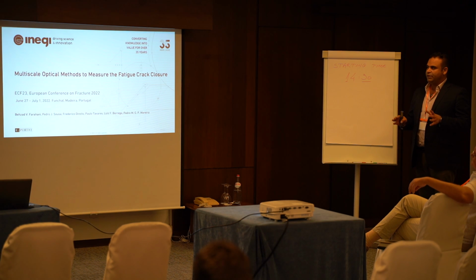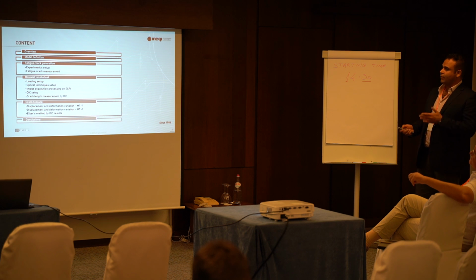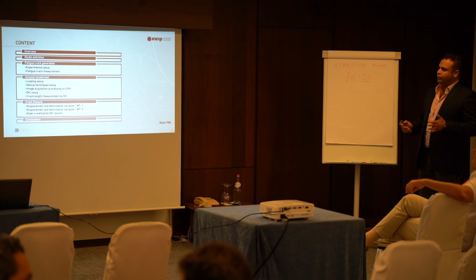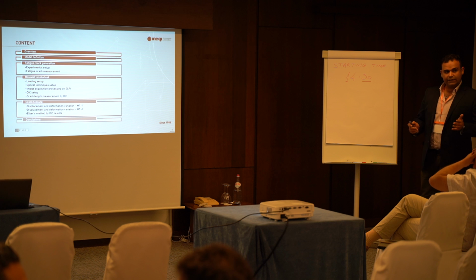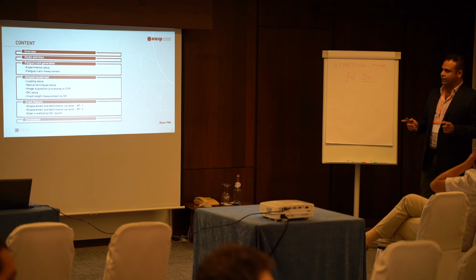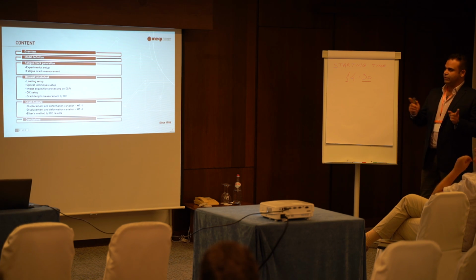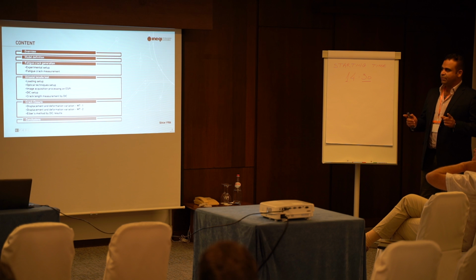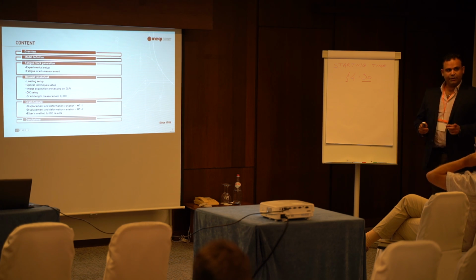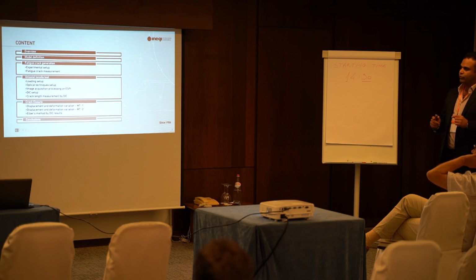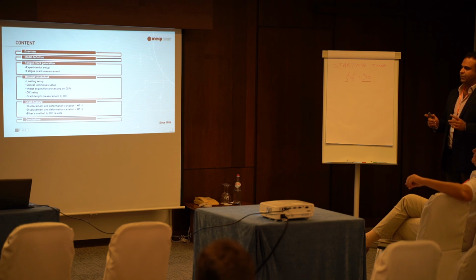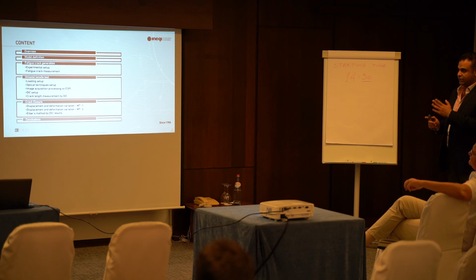Mainly experimental analysis. I'm going to start with an overview and model definition, and the fatigue test that I have done in order to open the crack. The specimen with the fatigue crack was then transferred to another experimental condition in order to open the crack and visualize it by digital image correlation and electronic speckle pattern interferometry, which is ESPI.